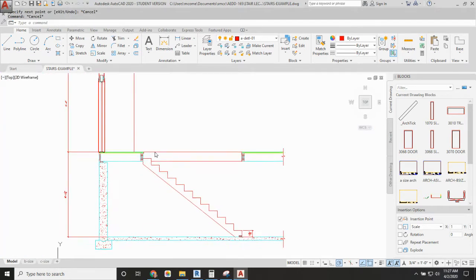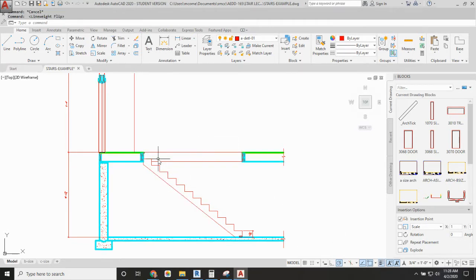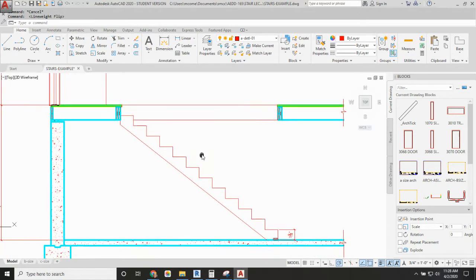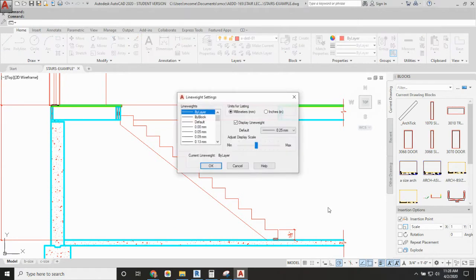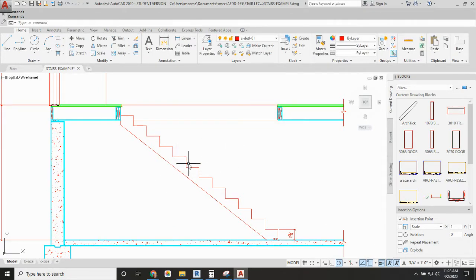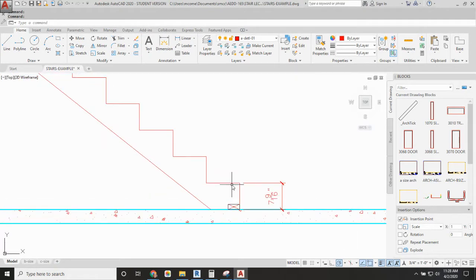And usually, like with a basement, you have walls that are enclosing the space, but this would be the opening here for the stairs, and this would be the floor system that we're seeing beyond. So that opening, I'm just trying to represent with thinner lines. So if I show the actual line weights, you can see that being represented here. So let me tone down that line difference. There we go. So to finish building this whole stringer, let's put that tread on top of there again.